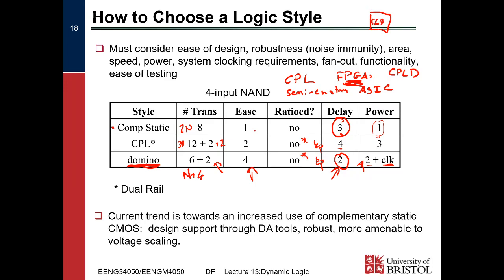We call them configurable logic blocks, and then we have something called a switch, right? Which multiplexes all the inputs to it, and multiplexes all the outputs from it, right? And so our configurable logic block might be made out of CPL logic, where it's static and very regular and highly compactable, without reducing the generality of the logic, and then we just configure what the specific inputs are.